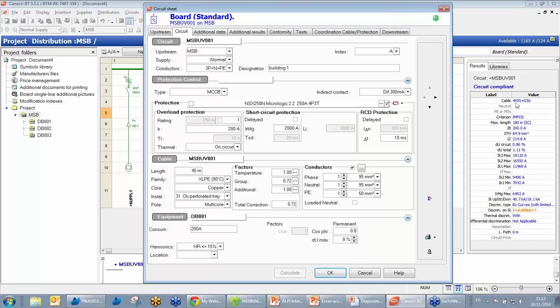We have got right here the cables. We have got also here the maximum length of cables protected. So as you can see, we can go up to 180 meters. Then we will see appear some short circuits. So it will be helpful also to find the best way to optimize your installation. You have got the cross section.